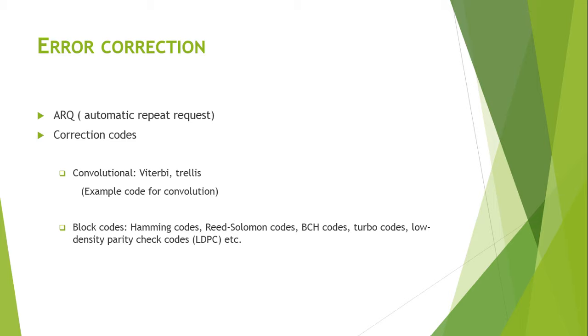Okay, correction codes. Error correcting code is also known as forward error correction code or FEC. They add non-essential data to a message so that multiple errors introduced in the transmission can be corrected. These are mostly used at the lower level of the communication stack. Since we are exploiting the channel capacity by adding the surplus data, the Shannon-Hartley theorem that I talked about in the introduction becomes crucial in determining error probability and SNR. The code rate is equal to K by N, where K stands for source symbols and N stands for encoded symbols. FECs are broadly divided into convolutional codes and block codes.